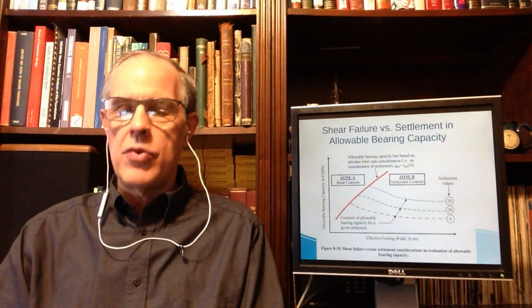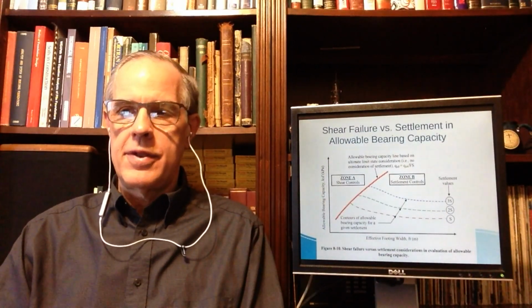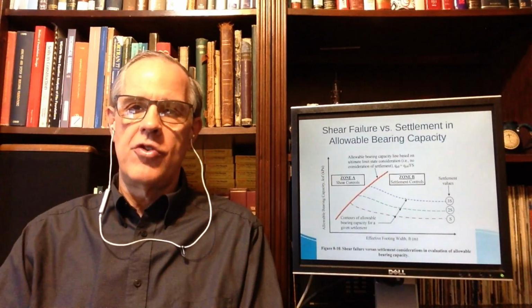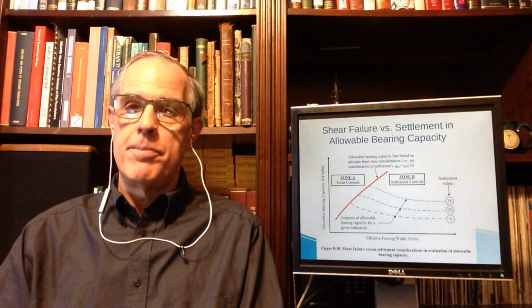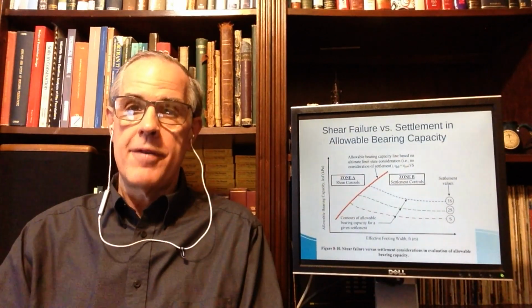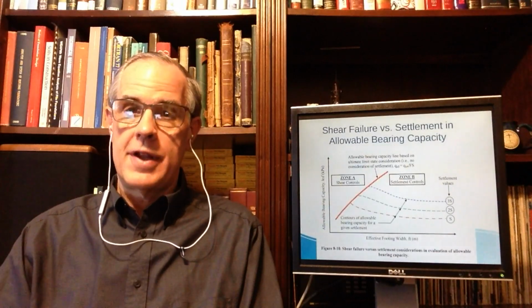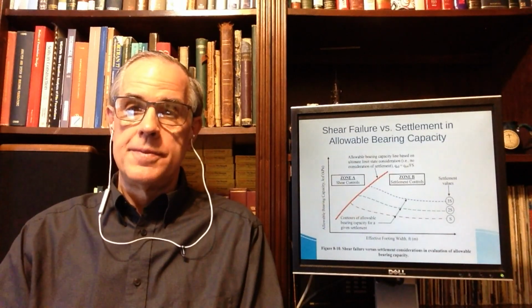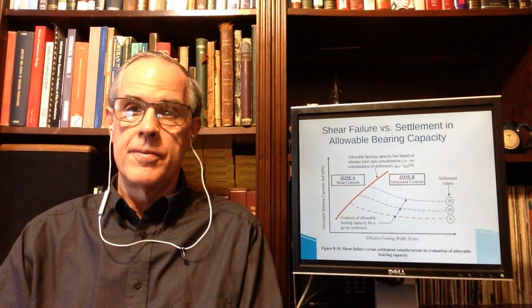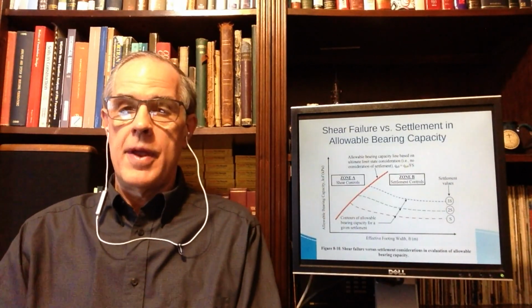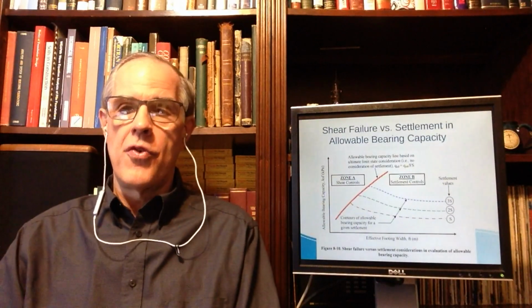I will note that one of the things that this kind of diagram teaches us is, generally speaking, the narrower a foundation, the more important bearing capacity is. And the wider one is, and particularly getting to mat foundations, the more important settlement is. So those are the differences between the two. And that's a big difference. I'm not going to get into a formal treatment.